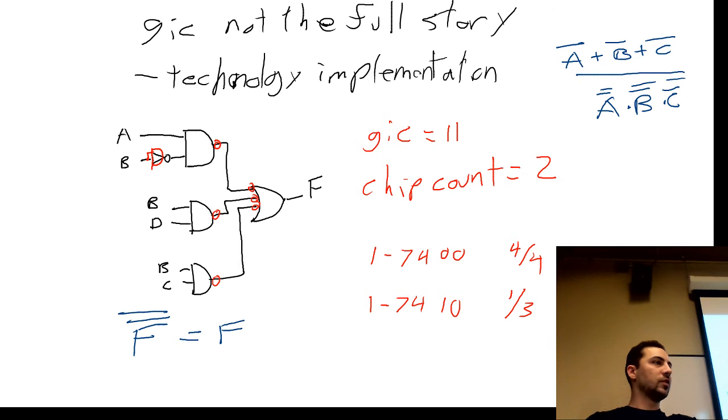Right, because you got to split the line, change the sign, so you get 2 bars, but that cancels out. So overall, that's NAND. Okay, so that really is a NAND. So everything is a NAND. Okay, we actually didn't have to change the circuit at all. I just added bubbles. But our gate input cost is 11, our chip count is 2.